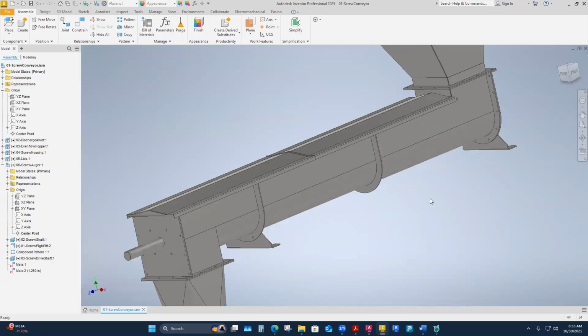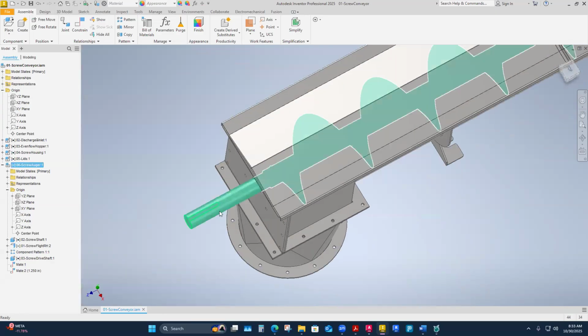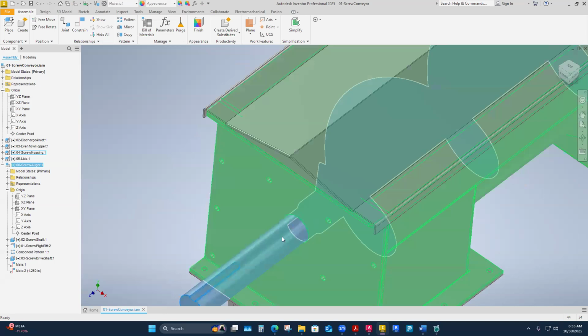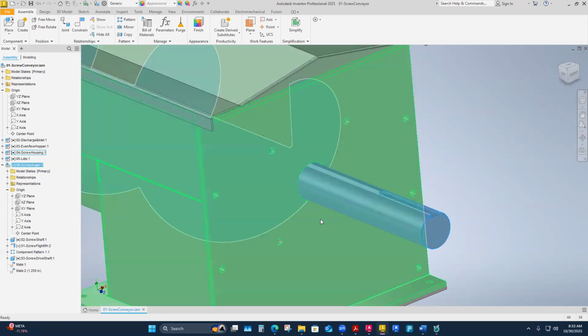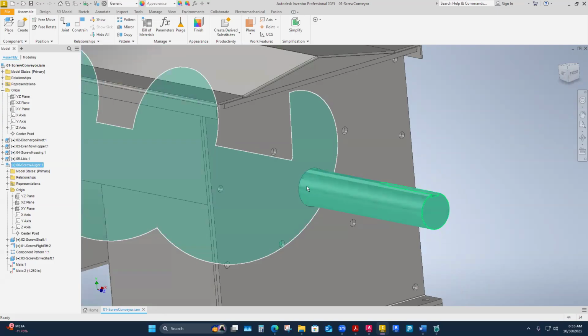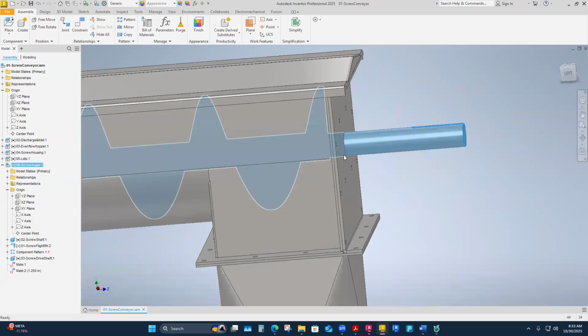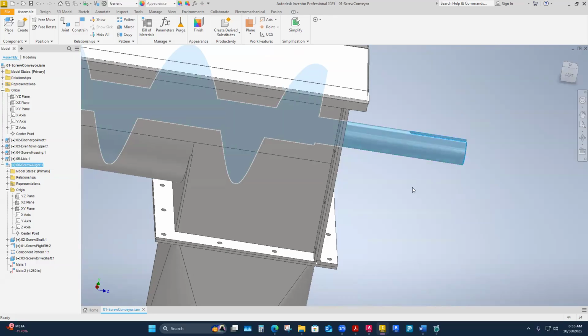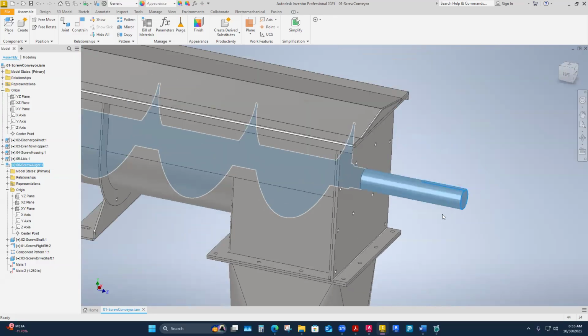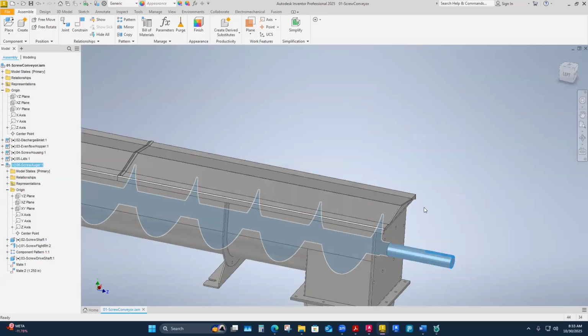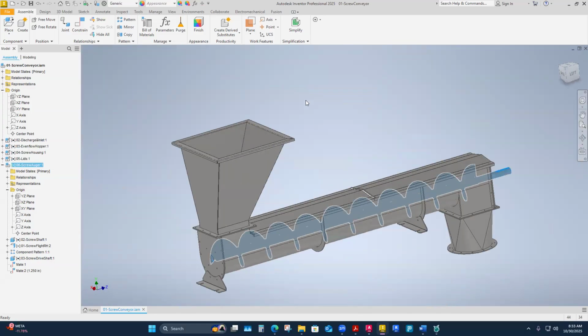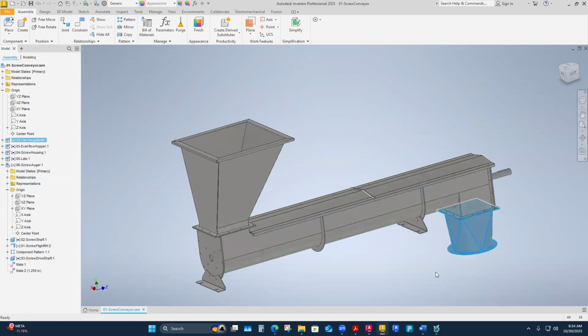And one end is going to be one end that has, oh, I've already started working on this shaft. So this one already hooks to the auger here. And so this one is ready for me to slide a bearing over the top of this shaft, and then to bolt it to this end plate so that this auger will be suspended in this housing. Then this is a long shaft, so I can hook a drive motor up to it, put some power on this thing, and let it spin. And then whatever I dump in the top of this hopper here, this thing will be spinning and it will auger that material down and out through this here. So this will be an inlet here and a discharge here.